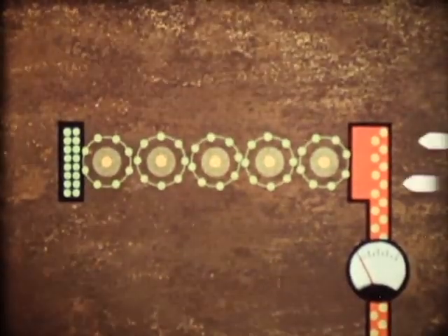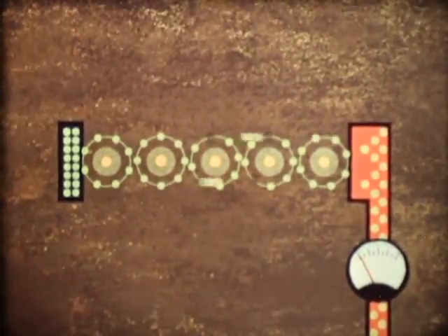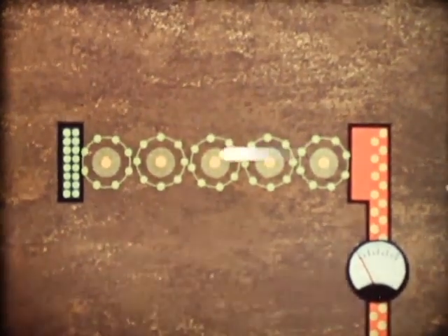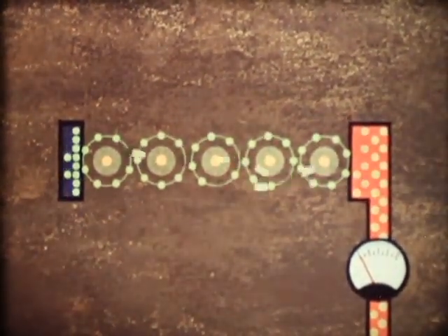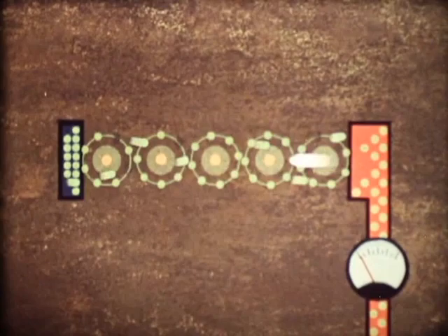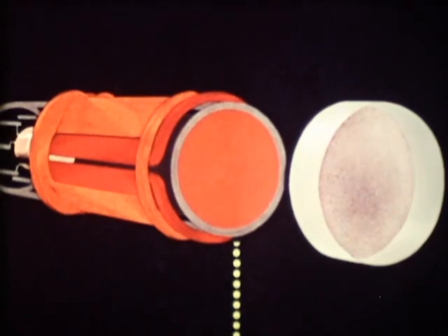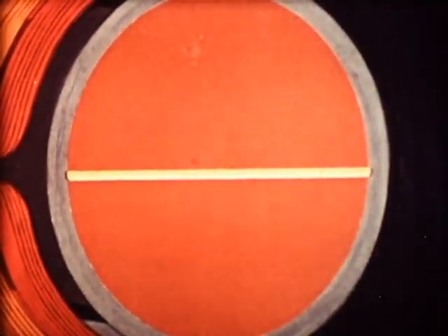Poor light produces only a weak charge current, as can be seen from the meter. But as the light increases, the current becomes correspondingly stronger. In this way, the intensity of the light is translated into small current pulses, not only within these small capacitors, but throughout the signal plate. As we've seen, the scanning process divides the picture into a large number of horizontal lines. Let us then consider what happens in the signal plate along one of these lines.